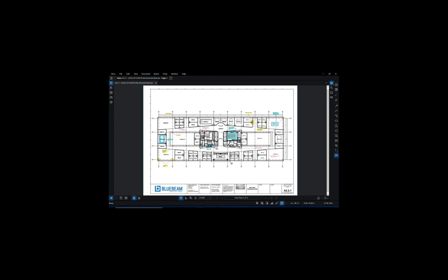And there's a setting within Bluebeam on the Mac side and the Windows side that you can have Bluebeam automatically open PDFs as soon as they're generated. So as soon as you publish from Vectorworks and you double click on the PDF to open it, you change that setting and Bluebeam will automatically open it for you.